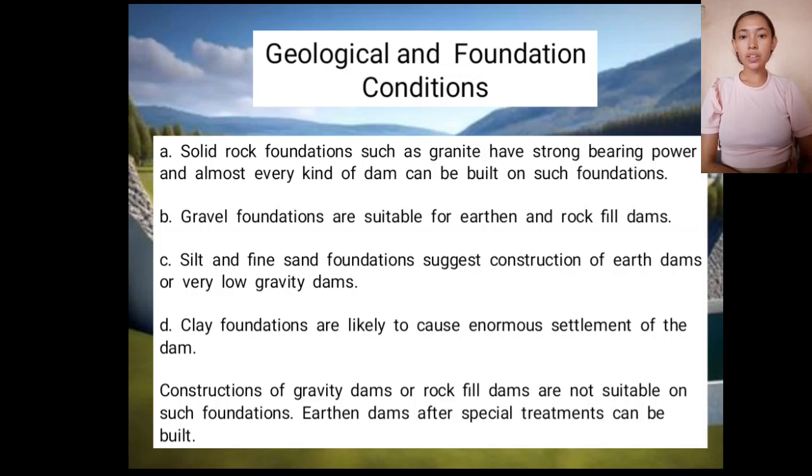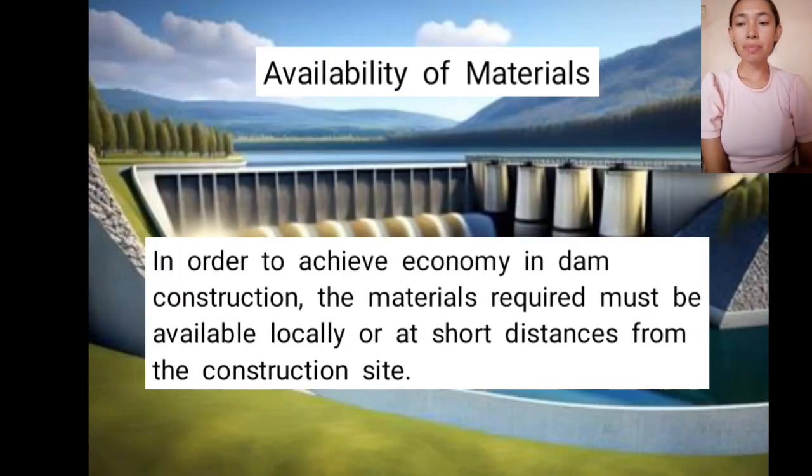Geological and foundation conditions. Solid rock foundations such as granite have strong bearing power and almost every kind of dam can be built on such foundations. Gravel foundations are suitable for earthen and rock-filled dams. Silt and fine sand foundations suggest construction of earth dams or very low-gravity dams. Clay foundations are likely to cause enormous settlement of the dam. Construction of gravity dams or rock-filled dams is not suitable on such foundations, so earthen dams after special treatment can be built. Availability of materials.